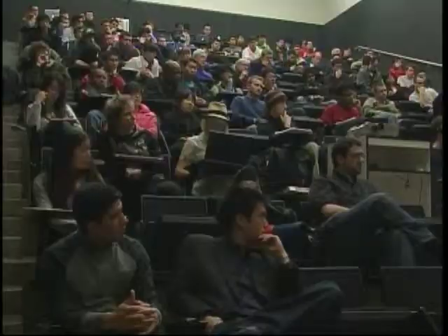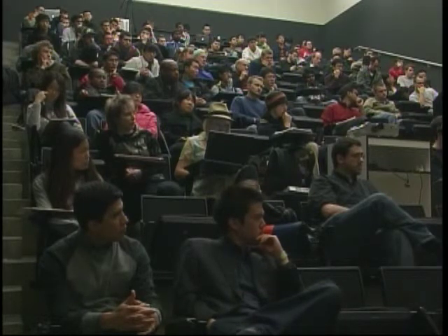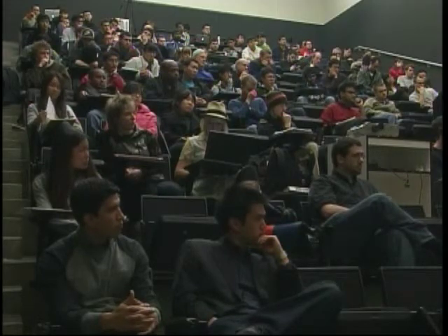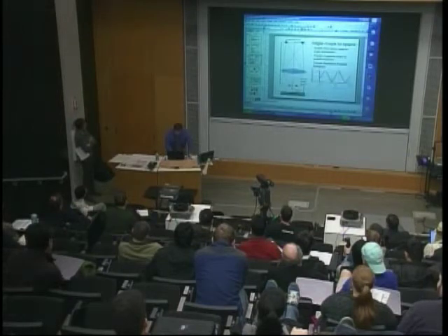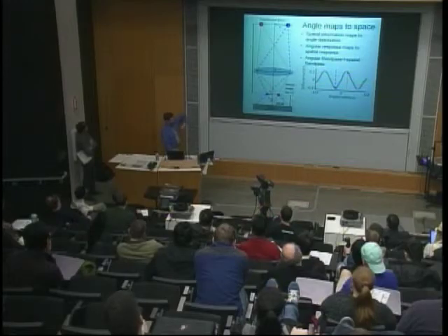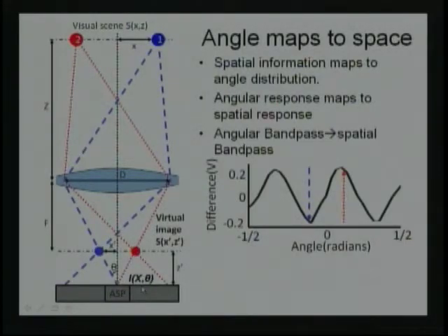So to get a reliable image out of what you're just talking about, do you have a range limitation typically? Or, for the depth mapping aspect of it? Yeah, so as you move farther away, essentially, I can point at a diagram, it makes a little more sense. Let's pick this one here. In this general image, what we're actually sensing when we do depth mapping is this depth here between the image and the plane. But there's essentially a gain term between this depth here and this depth here, and it's not linear. So as you move farther away, that gain gets worse.